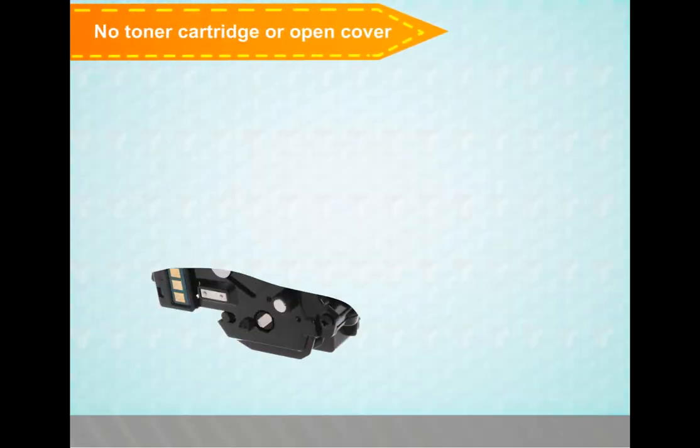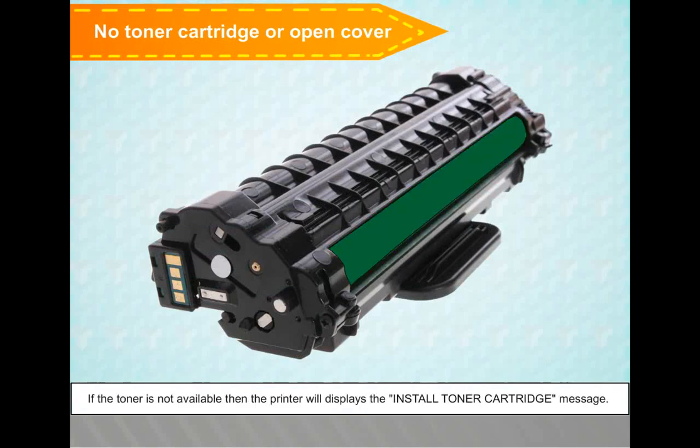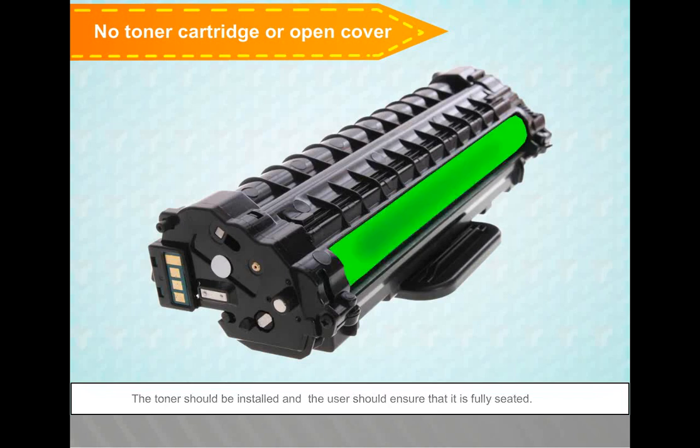No toner cartridge or open cover. If the toner is not available, then the printer will display the Install Toner Cartridge message. The toner should be installed and the user should ensure that it is fully seated. The high voltage power supply might also cause this error.